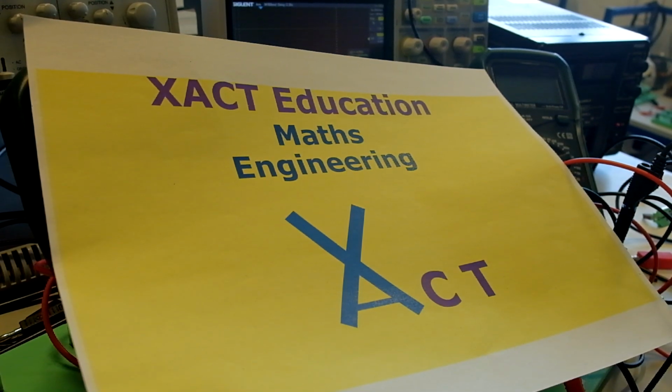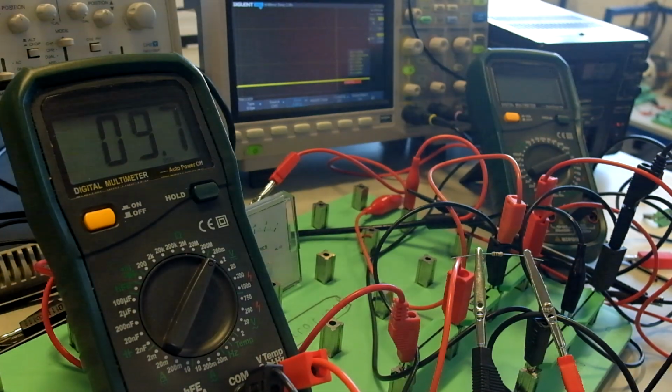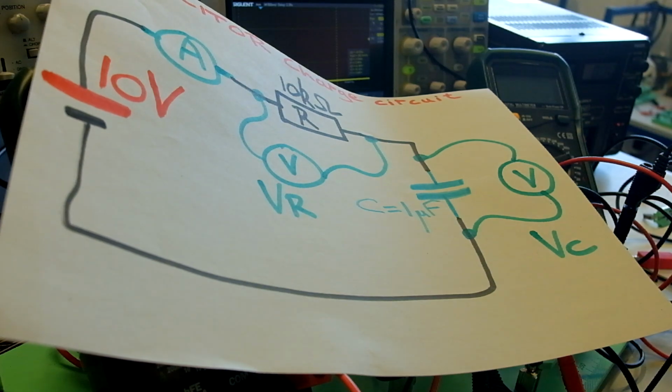Hi there. The purpose of this video is to ascertain by experiment the value of leakage current and leakage resistance through physical capacitors. All physical capacitors will have some sort of leakage current through the dielectric. Now that is anticipated to be in the region of microamps or less than microamps, and we're going to prove that by experiment. We're after orders of magnitude here rather than getting the values down to individual ohms.